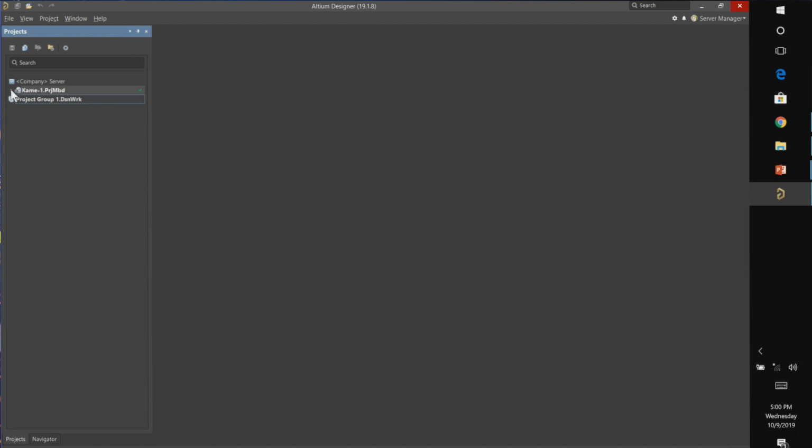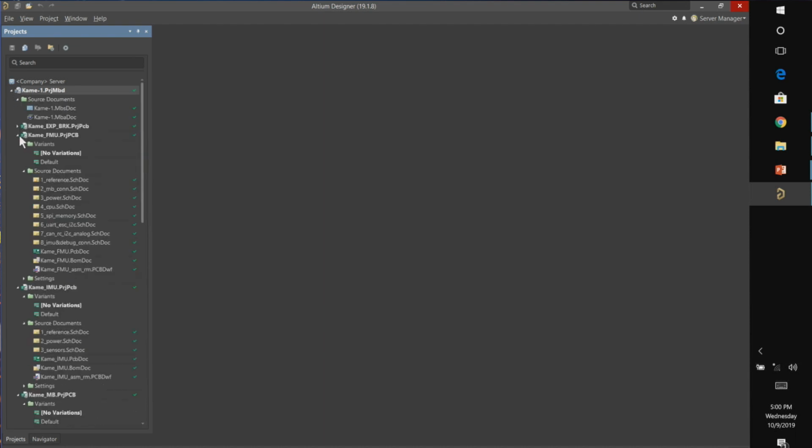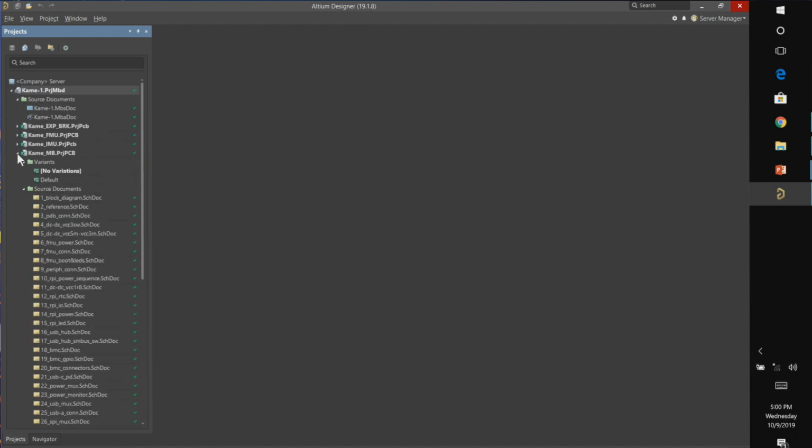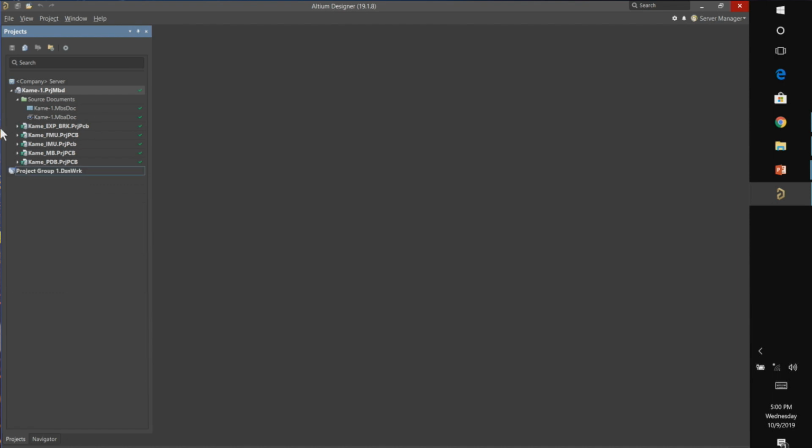But basically, within a multi-board project, you can reference existing lower-level projects. These exist as independent entities, so these projects you do as you normally do, but there's a way to create a top-level project that will access all of this information and then electrically tie it all together, and then it will give you the bill of materials for sourcing as well.